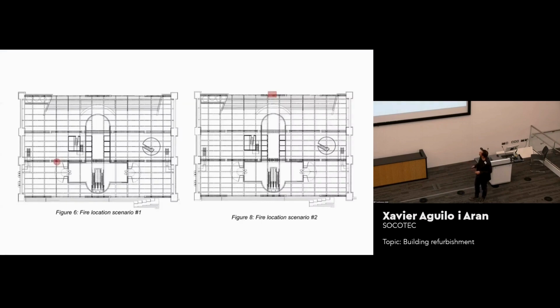So what we did here was to analyze the building, the steel structure, with a CFD model, computational fluid dynamic analysis, to understand which temperatures we can reach on the structure in the case of a fire. If this temperature is lower than a certain level, there is no problem because the steel can remain with all its faculties, okay? So we defined, per the place where we were doing the job and the overall ground floor, a fire case there that is red and a fire case there. So we defined the different specs for each fire to understand the level of heat on the top.